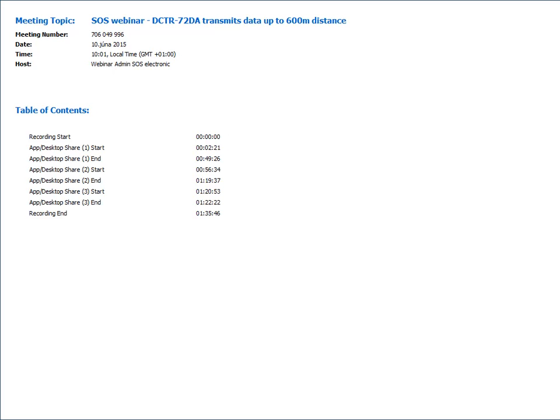let me put it this way, during the FRC, you have 40 milliseconds to communicate from the module to your device to download the data. And if this time is much longer, then you can preset it in the FRC. So if you have devices that read the temperature for 10 seconds, and we really have this kind of applications, then you can set up: okay, I will send the FRC, then I will wait for 10 seconds to do the measurement, collect the data, and send the FRC back. So this is covered.